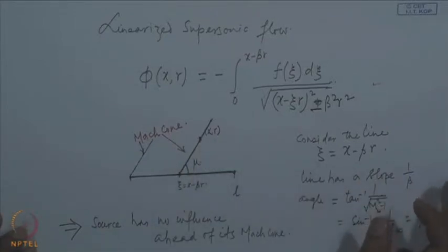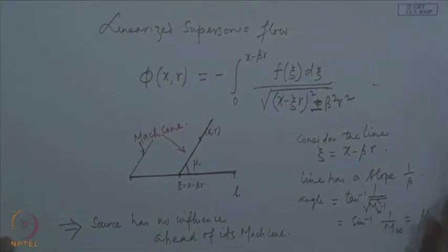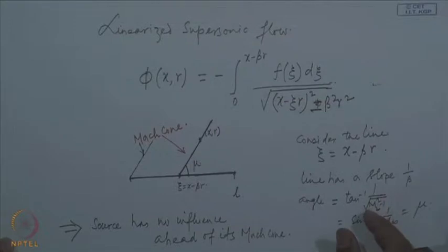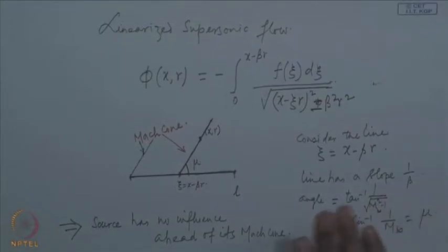We should see here a little difference from the linearized two dimensional flow problem. In the linearized two dimensional problem we have seen that a disturbance has no effect either upstream or downstream of its Mach line. The effect is confined to the Mach lines. However, in this axially symmetric case, there is effect over the whole region downstream of the Mach cone.